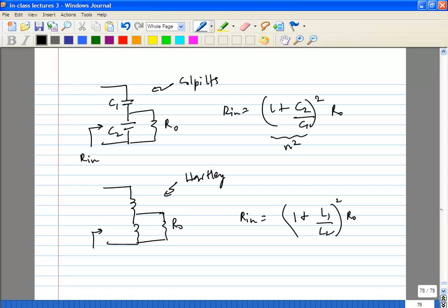Direct trade-offs, obvious things when you look at it. This is using two inductors, so of course more area. You might be able to implement a single inductor with a tap on it, so that will definitely save on area. We won't have time to look at this in class, but there are implications for noise, depending on which circuit you use.